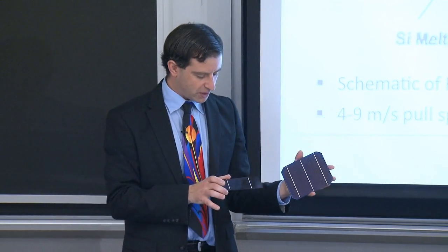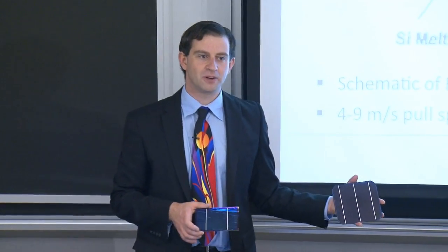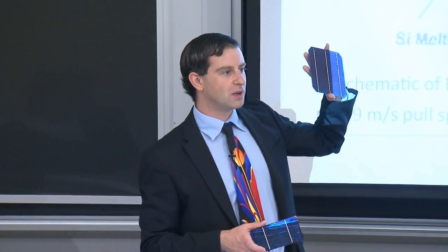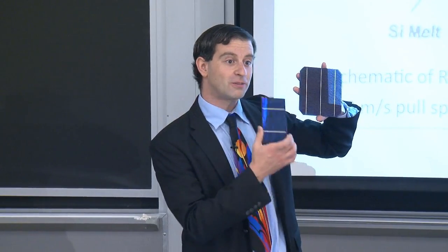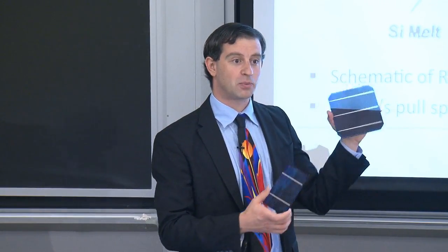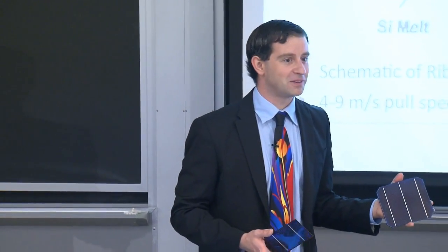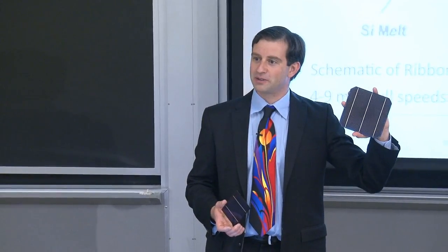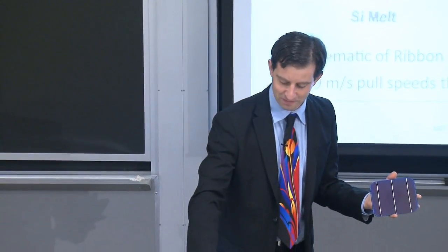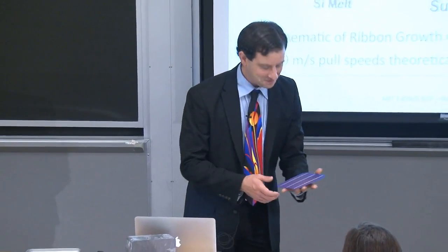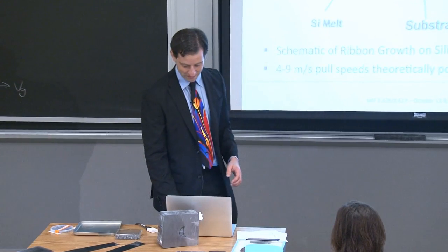Yeah. So the bus bars, the optimization of these bus bars, this one has 3. That's really to minimize series resistance. Because now out of a larger wafer, you have so much current flowing through it, being generated, that the series resistance through those very thin metal wires would end up resulting in large power losses, essentially heat instead of electricity. And so they added the third bus bar, even though it increased the shading, to reduce the series resistance losses. So you can see these optimization problems are used quite frequently in solar.